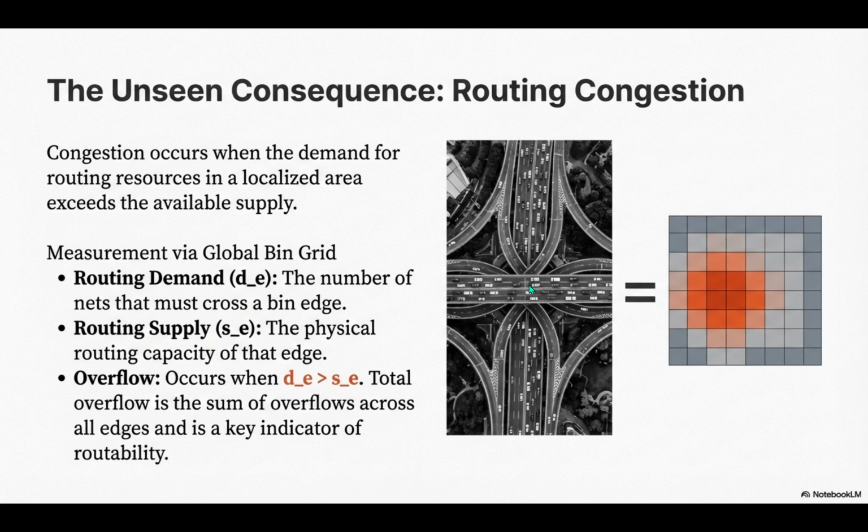You might have minimized the average demand across the whole city, but you've accidentally created this localized hotspot, a region where the demand for routing just skyrockets way above what the local supply can handle. So, this is the congestion paradox in action. It is. Minimizing wire length may, and in today's advanced nodes, it will create locally congested regions. The algorithm effectively starves certain areas of routing resources to get that mathematically perfect global average. And those starved areas become completely unroutable.